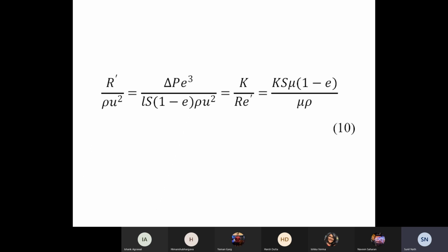Then in between Reynolds number 1 and 500, we have the intermediate region. But generally, instead of saying that the slope is different at every point, this region in most books that I have seen is approximated as having a constant slope of minus 0.25.